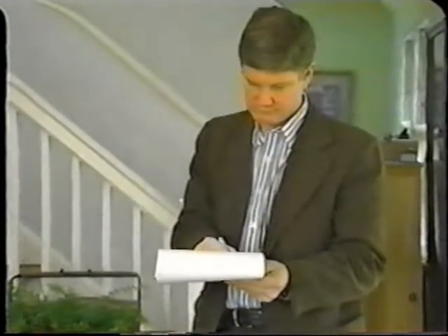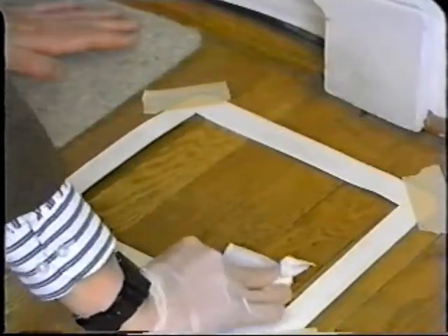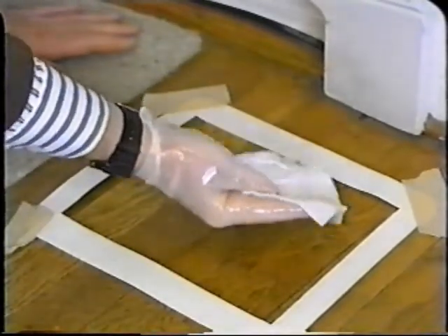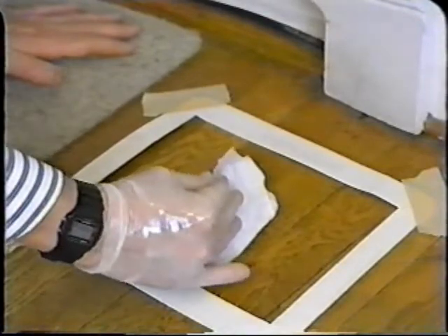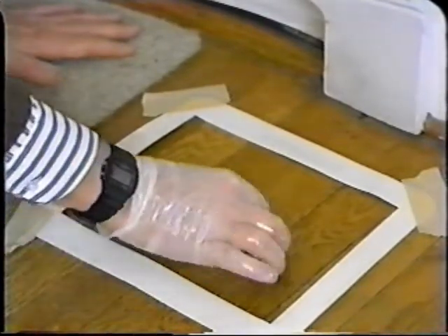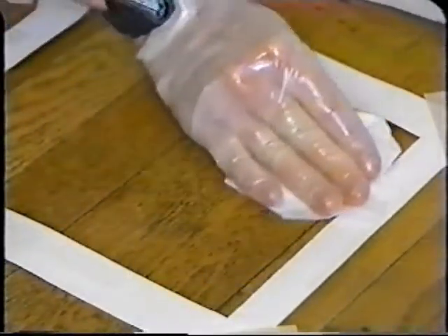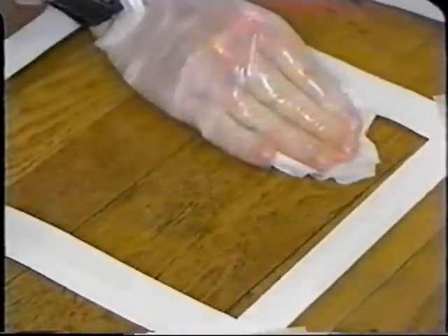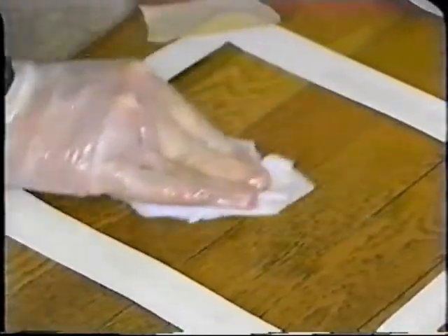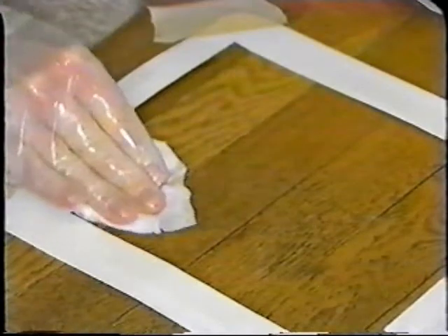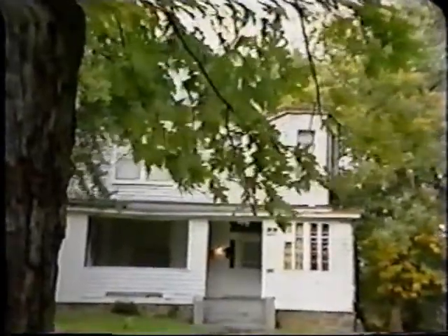The clearance evaluation includes a visual examination of the entire work area and dust sampling of certain components, such as floors, window sills, and window troughs. You should be familiar with the federal clearance standards and any local standards that are in effect in your area. Should a dwelling unit fail the clearance tests, additional cleaning and possibly some work may be necessary. Once the dwelling unit passes clearance, the lead hazard control work is complete and the residents and their belongings may re-enter the work area.